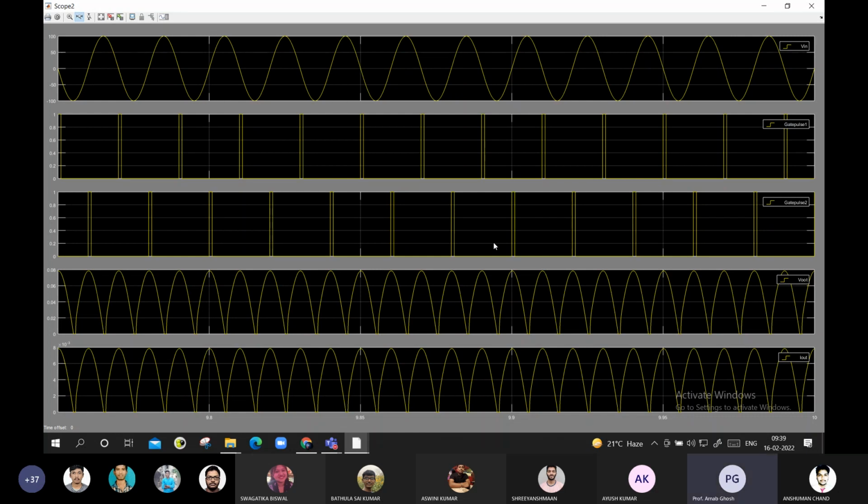Thyristor will be turned on for 180 degree. In practical conditions, we will get very little voltage. You can see in the graph, it's from 0 to 0.08, almost zero voltage. And the current is also coming at 10 to the power minus 3. Basically, it should not come at all. It should be 0.